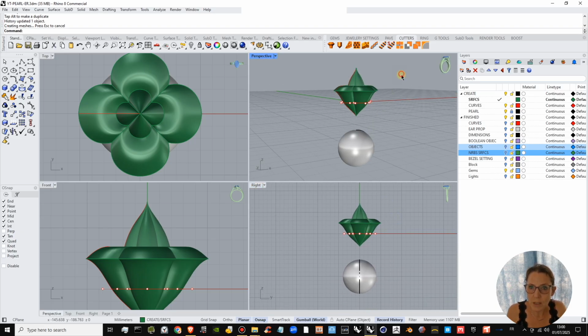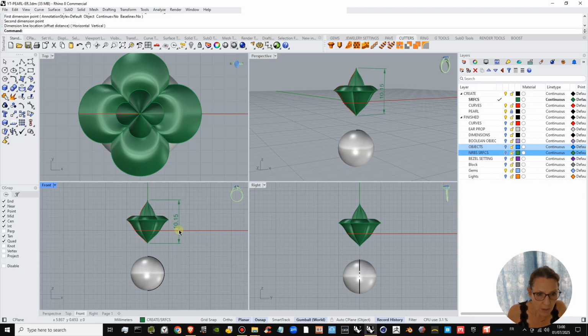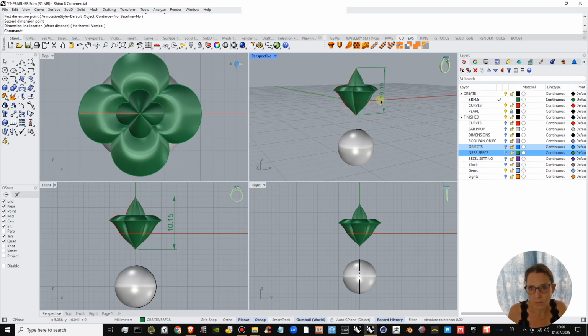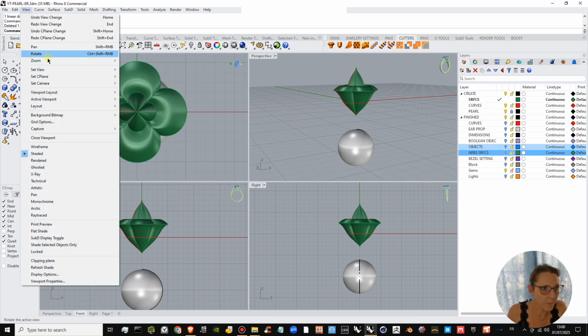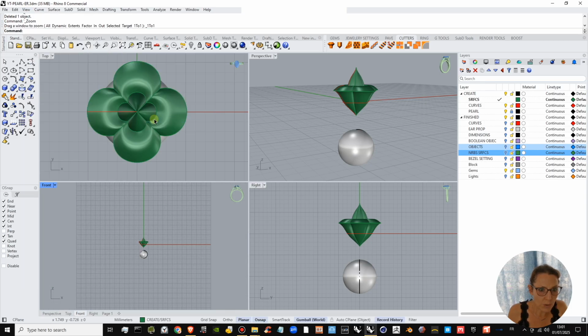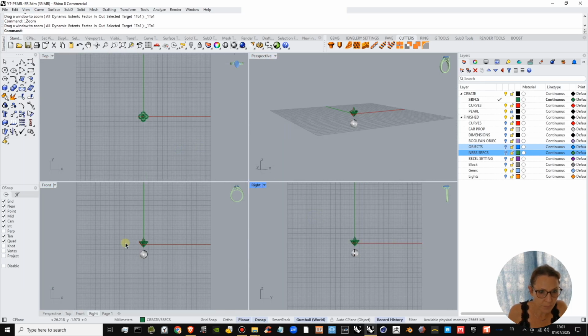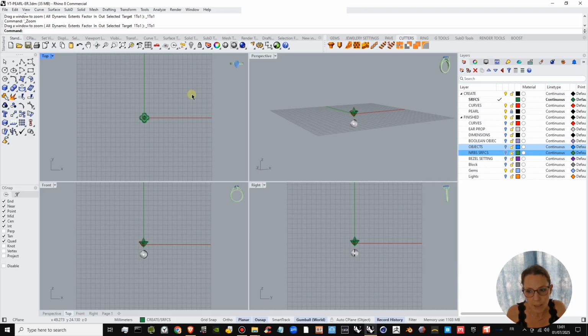So at this point I'm just going to have a look at what the dimensions of our object are here, and it's about a centimeter. That's good. If you ever want to know how big something is going to be when it's finished, what helps is to zoom 1:1 on your screen. It gives you immediately a good indication of how small your object is for real, because when you work in large scale like that, or when you work zoomed in like that, you tend to lose perspective on how small the objects you make can be. What also works is to print your objects out scale 1:1.